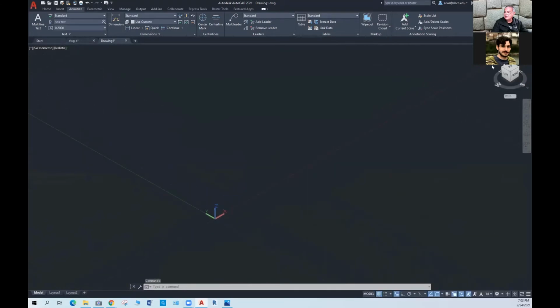Then notice that if I move the cursor to the upper left corner of the cube, I see a little house. If I go to a view like this and I want to go back to the home view, I can click on that home icon and I'm back on the home view that I just defined, right? So that's how we navigate there.